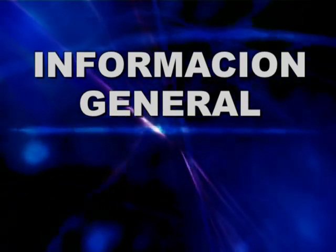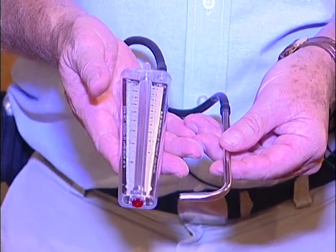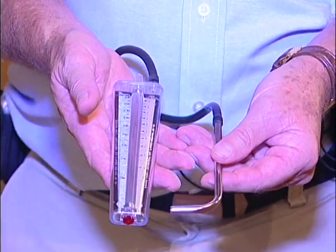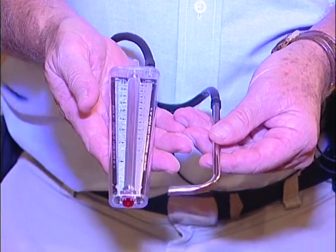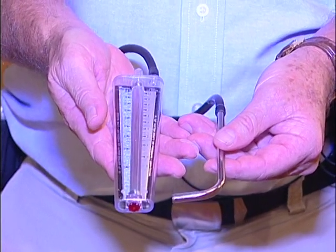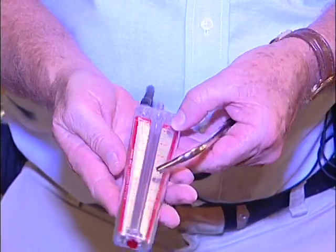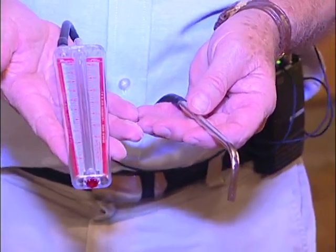This is the air meter that we use to test the pressure or the airspeed entering the house. If you look on the black side of the instrument, it reads pressure in inches of water. If you turn it over and look at the red side, it reads air velocity in feet per minute.